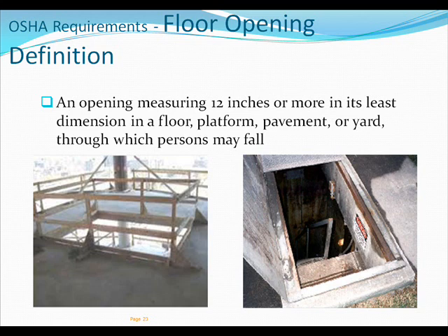Floor opening definition. An opening measuring 12 inches or more in its least dimension in a floor, platform, pavement, or yard through which a person may fall. All floor openings must be guarded or covered regardless of fall distance.